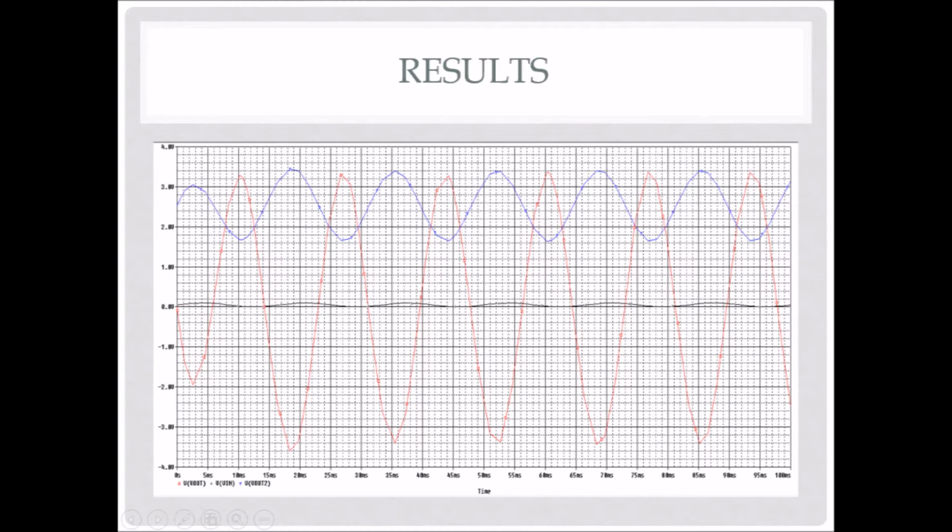The black line is the input into our preamp, the blue line was the output of our preamp, and the red line was the output of our power amp. The preamp continued to show similar gains to what we showed in our original schematic, as did the power amp, for a total gain of around 79 volts per volt.